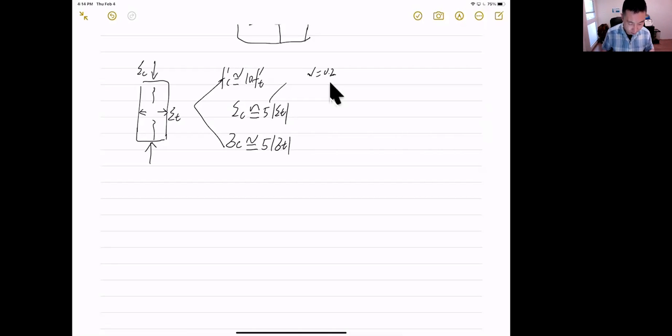All right. So coming back to this restraint effect, the restraint provided by the steel plate. Because concrete tries to expand horizontally, and steel closely touches the concrete surface under very high compression, the friction force is pretty high. So steel can restrain the concrete from expanding. That will offset some of this tensile stress, so that will make the concrete crack later. So we're going to have a higher apparent stress.